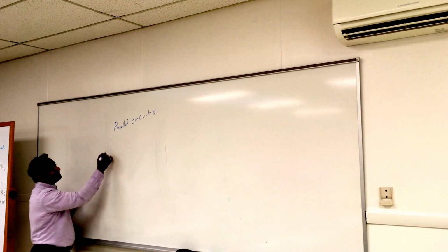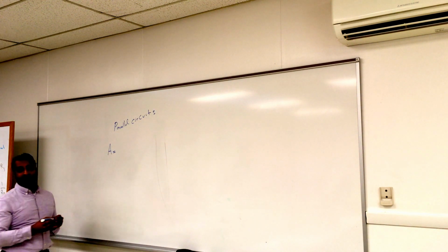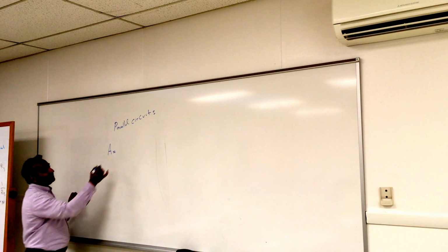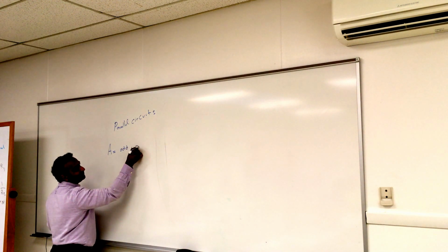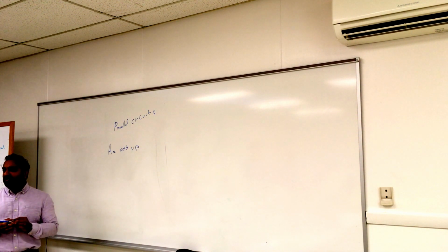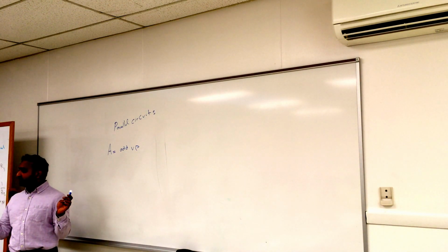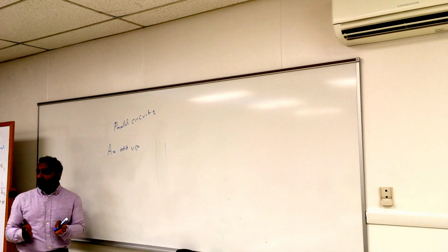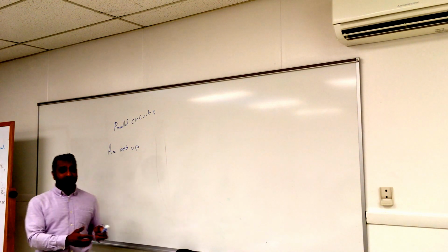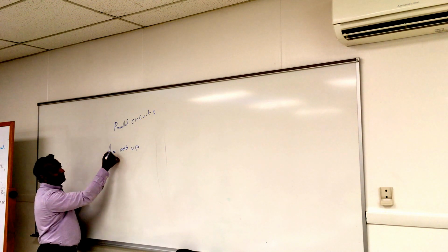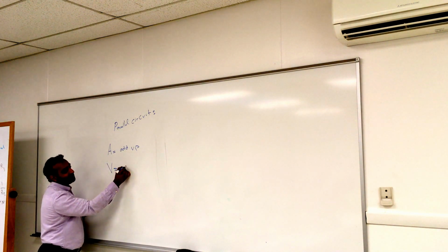So first thing, the amperage. They add up. So the amperage makes sense because again the current is diverging. If you have a flow of water, the branches each get their own flow. We agree? So the amperage will add up. The voltage stays the same.